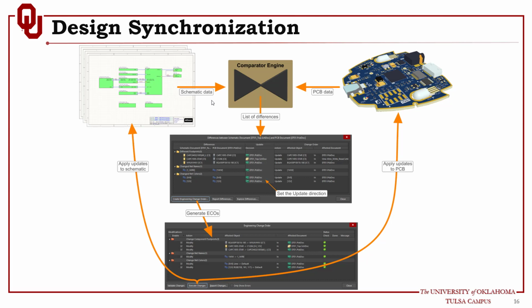Sometimes an engineer might change something on the schematic and forget to commit that to the layout, and release the layout board without committing the change of the schematic. And then when it comes to implementation and testing, oh, there is a big problem, because one of the nets was changed on the schematic but was not committed to the layout, and it's not right. So there is a discontinuity between the schematic and the layout because they are not synchronized.